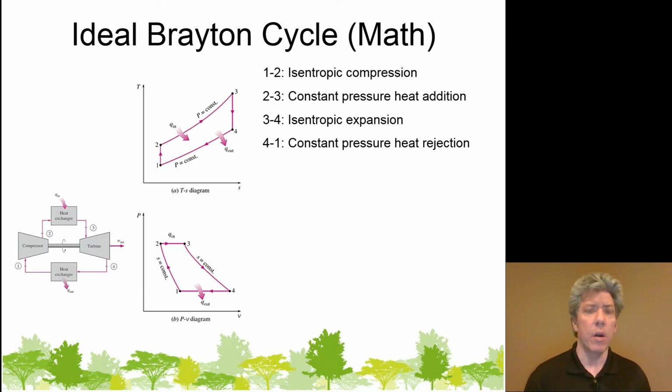Now you'll notice that all three cycles involve compression and expansion processes that are ideally isentropic. Now of course how isentropic, how reversible these things actually are depend on the nature of the engine itself, how it's designed, how much heat is wicked away during these processes, and of course how reversible they are. How well do these devices perform in terms of reversible expansion or compression of the gases. It depends on the design. An engine with much more friction is going to be less reversible. An engine that allows gases to expand quickly will be less reversible because it's more unrestrained expansion of gases. So just something to think about.